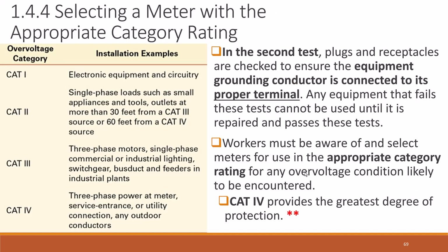The second test I've got listed over here: plugs and receptacles are checked to ensure the equipment grounding conductor is connected to its proper terminal. So that little tester that I was showing you for the testing of the GFCI tests for continuity also, and tests to make sure that the outlets are wired correctly. So it's a handy little tool to have. It is not expensive.